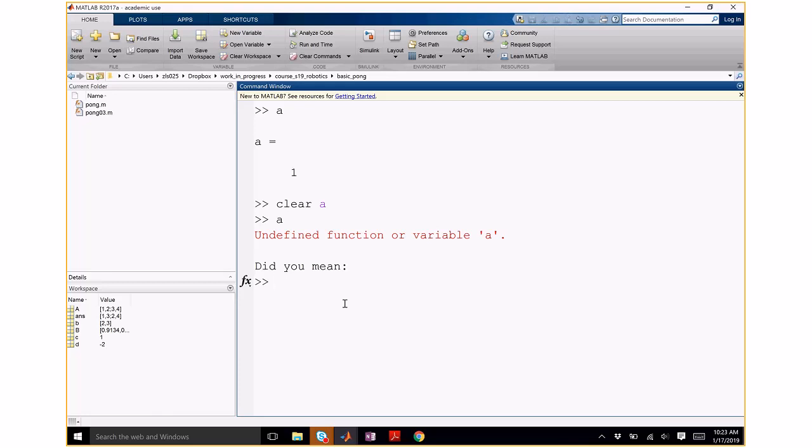Now you could do plotting. You do this with your calculator, but you could also do it with MATLAB. Let's say we want to plot the sin x function. First I need to create points, right? So if I say sine of x, I want x to be from 0 to say 2 pi. The command which does that for you is linspace, 0. It actually gives you a hint how to use it. This was not done in previous versions of MATLAB. So 2 pi. What this does is essentially puts dots from 0 to 2 pi.